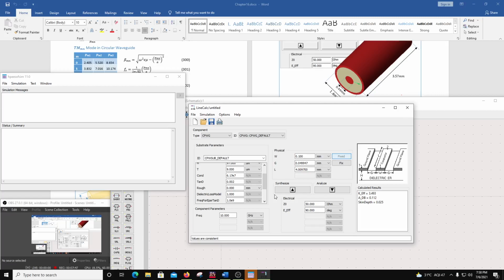So if you have a microstrip design, now you go and proceed and do a CPW, so you have a rough idea of what the W should start with. You cannot just put here whatever you want and then try to create a line, because 5 mm is much larger than the height. So the golden rule is the gap and the width of the line is much smaller than the height. The height is 97 microns. Okay, so I'm putting width to be comparable to that, and then there is a gap which is computed, and the length for this 10 gigahertz.